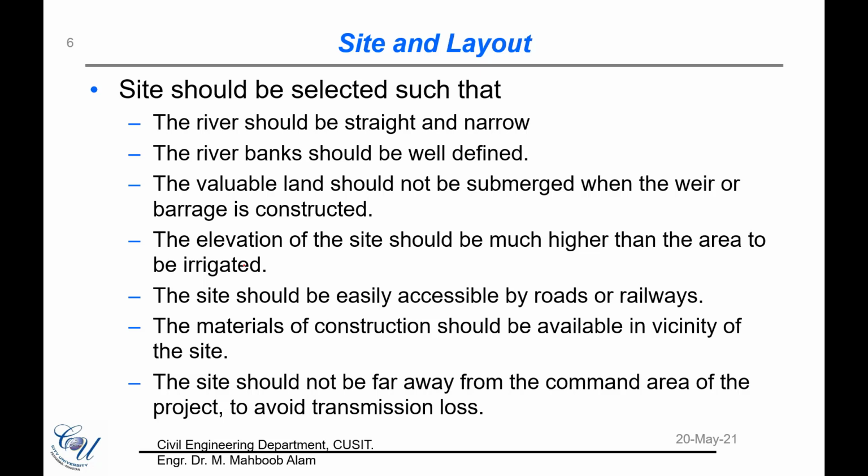If it is easily accessible, it would be easier to transport the construction material. It would be easier to transport the different machinery that is required into the diversion headworks. For example, the larger gates, which usually stop water from entering a particular area. So a lot of heavy machinery that is needed in the diversion headworks need to be transported there, and we therefore look at the area so that it is accessible by different ways of communication.